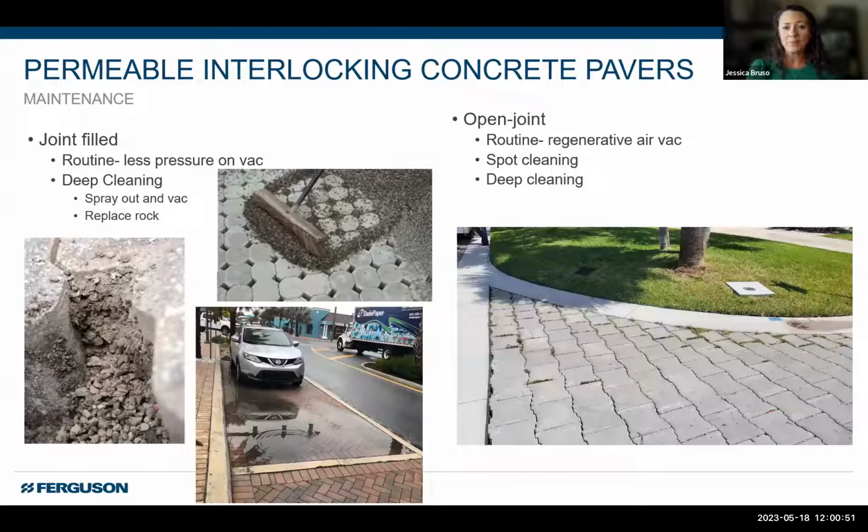Now, our open joint pavers, with our routine maintenance, again, regenerative air vac, it's going to be really good. We have what's called spot cleaning, again, with the pressure washer, right? So here's an area, and we talked about before, and I have more pictures of it coming up. But essentially, we tend to see a lot more deposits when water's entering into that porous area.